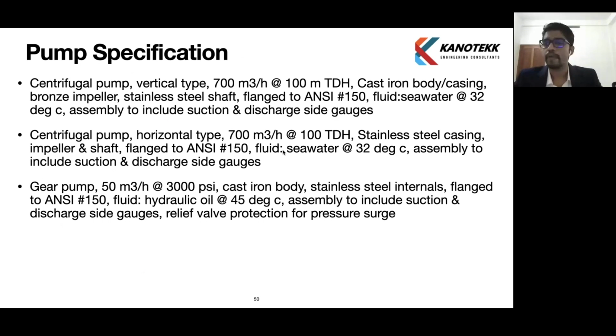So now we may have a doubt: why are centrifugal pumps used in the cargo system or in the oil pumping system in marine vessels or the oil and gas sector, etc.? Because of the high flow rate, we use centrifugal pumps. We design the pumps to be suitable for high viscosity in such conditions.